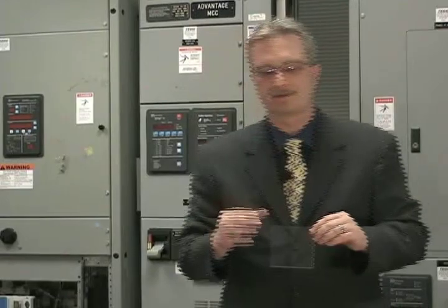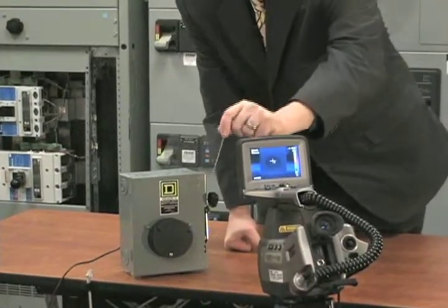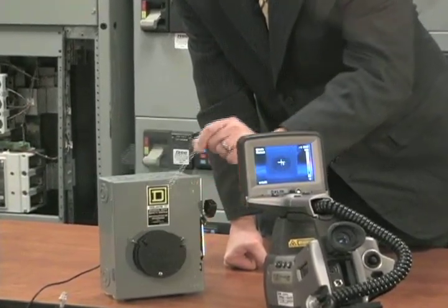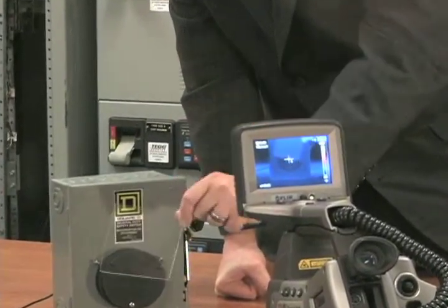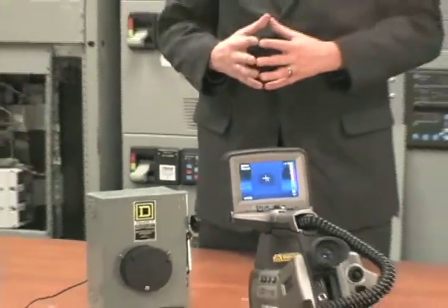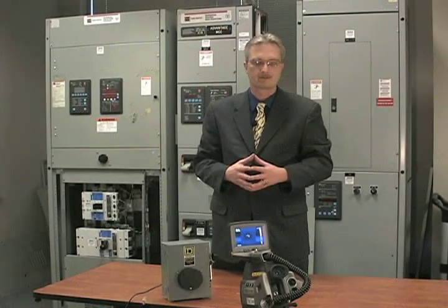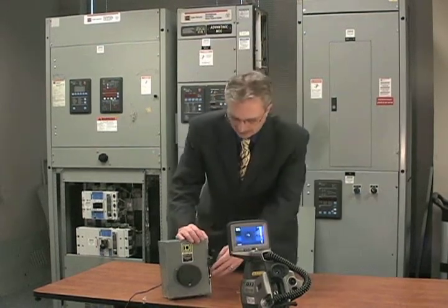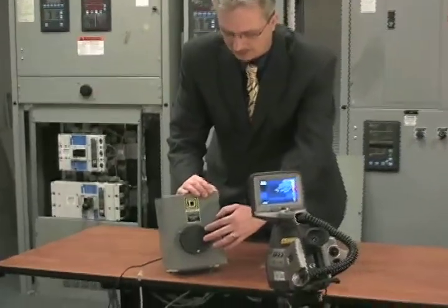But if we look back at the infrared camera, a piece of plexiglass is something that the camera cannot see through. An infrared window has to be made out of a special material. Some certain polymers, certain crystals. An infrared window is made out of a material that the camera actually can see through. The infrared window that I have installed onto the switchgear is made by Iris, and it is a polymer. It's a type of plastic that the infrared camera can actually see through.